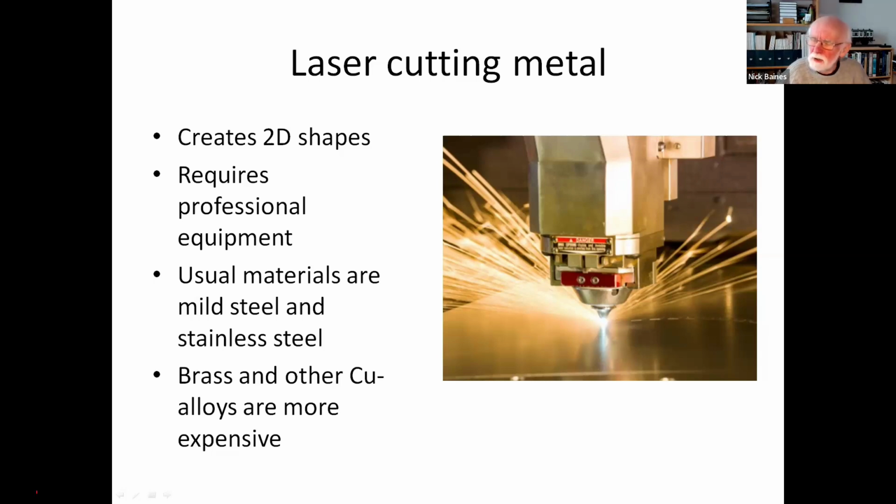People tend to raise their eyebrows a little bit when I say I use mild steel. I actually like mild steel. It's soft enough that I can work it perfectly all right. It's hard enough that it doesn't deform with the occasional knock or ding. And it soft solders very well.